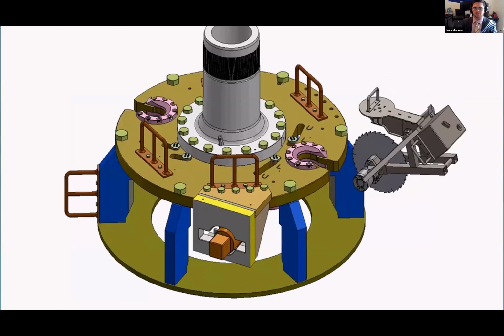I now want to talk about our hydraulic system that we use. We used a 4-way, 3-position spool valve. As you can see in the image, it's a tall stack of different orientations. The middle orientation is neutral, which you see now. It allows the hydraulic supply to be on, but the motor is not rotating, or the saw is not rotating.